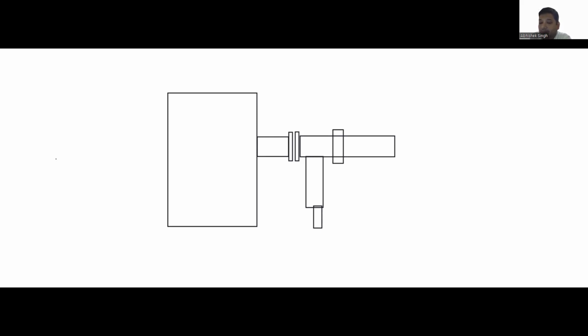We'll put all the values, run the WRC calculation in PV Lite, and consider that we have designed for that load. That load will be given to the piping department so that they can restrict their nozzle loadings within that limit. Making sense?